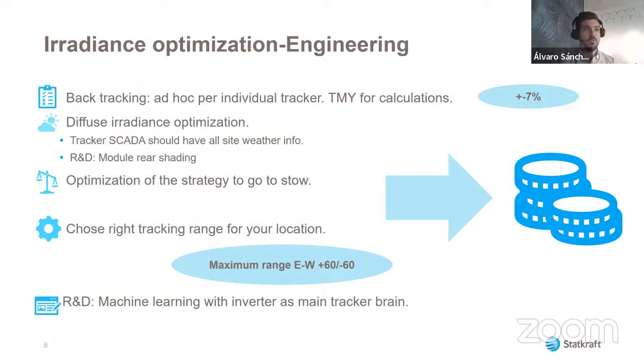Something also quite important that I mention here is to always use the TMY database for calculations, because when we have used synthetics or any other ones for the trackers, it didn't work very well, and we have seen very big differences. Sometimes the TMY is expensive because you need to pay for that. It's not free in general, but I think it's worth it when the project is getting solid, because you can have an impact of 7%.